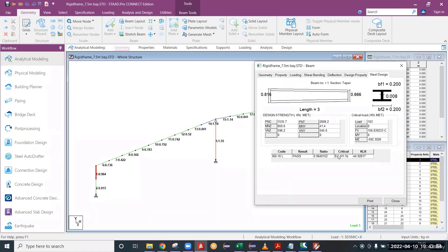H1-1B refers to the combined flexure and shear. G refers to the shear only. H1-1A refers to the buckling. So for H1-1B, you have to increase the depth of the web or increase the thickness of the flanges. Clear? And if this is critical in G1, G1 means you should not touch the web thickness.